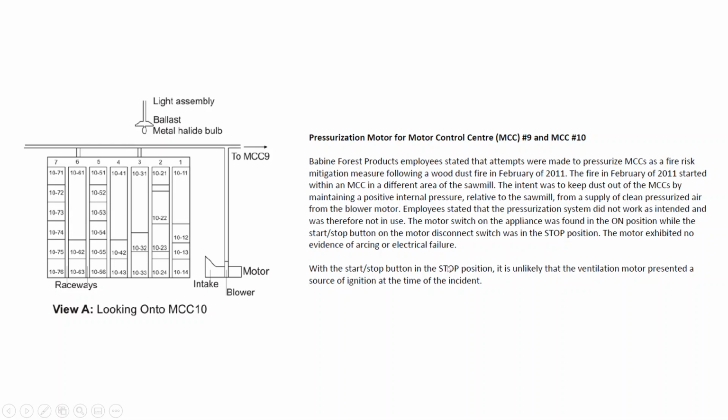Now, in the statement here, it says, employees stated that the pressurization system did not work as intended and was therefore not in use. The motor switch on the appliance was found in the on position while the start-stop button on the motor disconnect switch was in the stop position. The motor exhibited no evidence of arcing or electrical failure. So, with the start-stop in the stop position, it's unlikely that the ventilation motor presented the source of ignition at the time of the incident. What they're saying here is that the pressurized system was not operational.